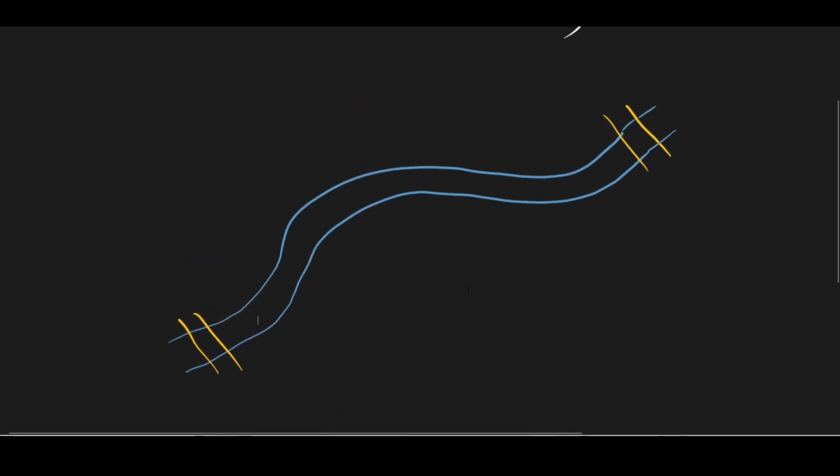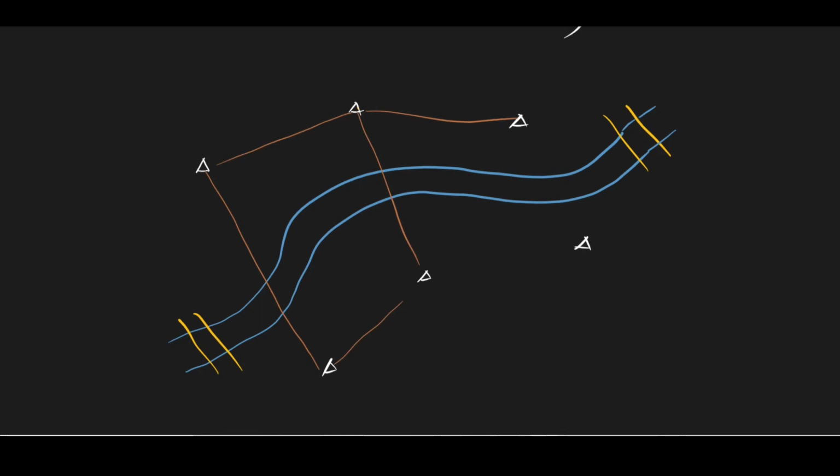So the typical approach doing this type of project is to establish your control points first. You have a control point here. Say it's just a very rough estimation right here, and then you observe, of course, right? Let's use another color. Let's say you observe these points here. So in this case, this is a chain of quadrilaterals, as you will see. Okay, chain of quadrilaterals.